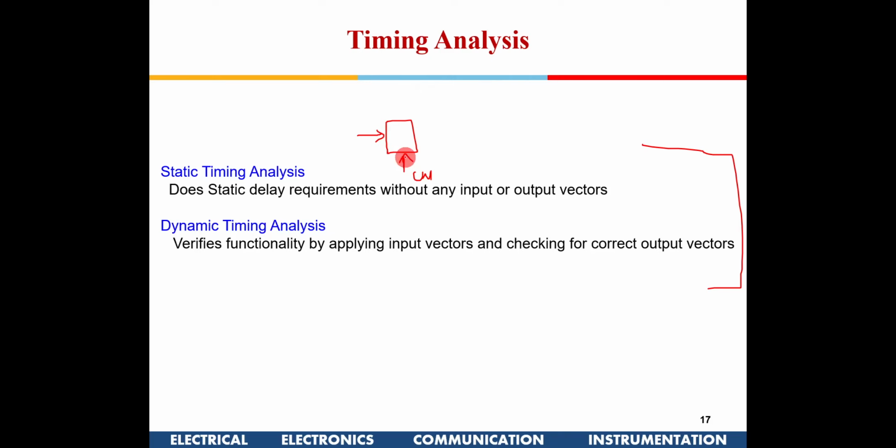It's a positive edge triggered clock. You may say the moment the positive edge has come, the data is captured and now I can change it. No, there is something known as hold time. There is some definite time required for the data to be captured. That is known as hold time. So is any violation happening at the desired frequency of operation? Those kinds of analysis will be done in timing analysis, and this aspect will be covered in detail in the other course.